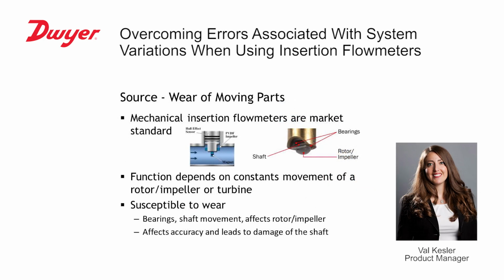In addition to insertion types, the most common in these types of applications are mechanical insertion flow meters. They're really what we've seen to be the market standard. They can vary from paddle wheel to turbine, and they depend on the constant movement of a rotor, an impeller, or a turbine in order to get you the velocity and therefore the flow of your application. The issue that tends to come with mechanical type flow meters is that they are susceptible to long-term wear.